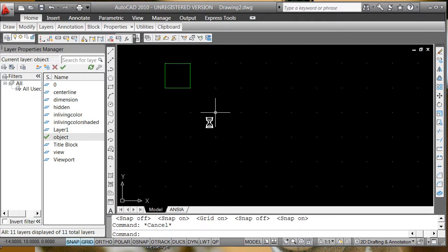That you will see at some point when you're drafting, that grid or snap will get turned on arbitrarily, it would appear, by AutoCAD. If it's jumping around like that, there's a pretty good chance it's because you're snapping your grid around. If you notice along here, you may have icons. I like the words, and I will tend to always be drafting with them off until I tell you otherwise.